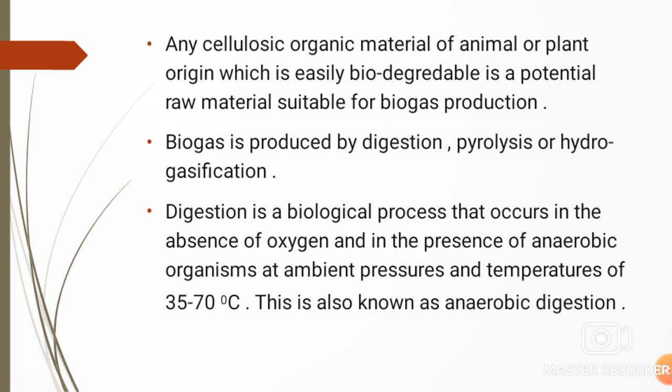Biogas is produced by digestion, pyrolysis or hydrogasification processes. That is, digestion means the anaerobic digestion; pyrolysis is the decomposition of the biomass into bioenergy in the absence of oxygen; or the hydrogasification process. Digestion is a biological process that occurs in the absence of oxygen and in the presence of anaerobic organisms at ambient pressures and temperatures of 35 to 70 degrees Celsius.